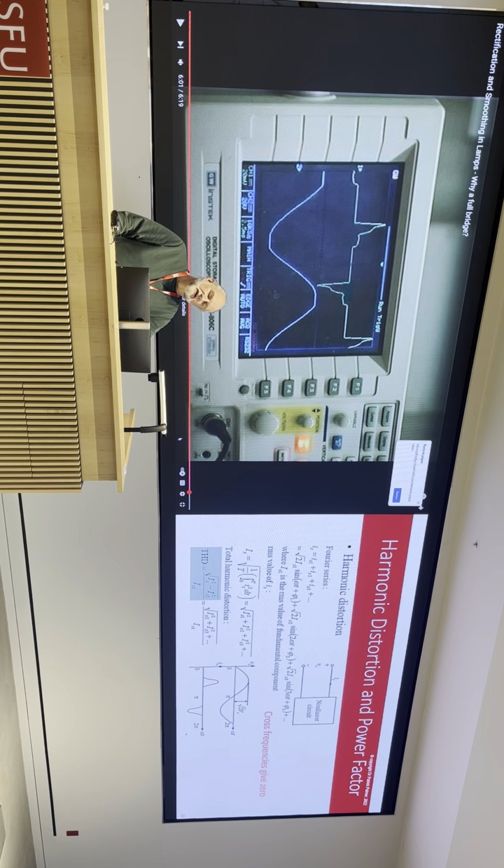Oh, of course. You guys should have been helping me here. You've got two frequencies. So what do you get? You get the sum and the difference. So you get a 4 omega t and a 2 omega t. So both of them will be sine waves. So your S is both of them sine waves. There's no average power, okay? Because you get the sum and difference frequencies there. Do you remember that? Adding modes and things like that.